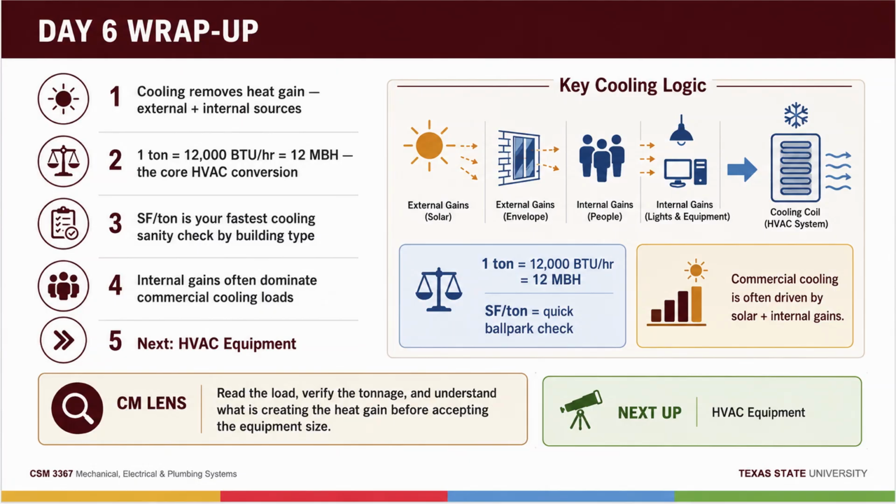Plain language. Common ways to lose points. Learn them now. Using R values straight in the equation without flipping to U. 1 over R, always. Forgetting 3.412 and treating watts like BTUs. Leaving out the latent loads entirely and dividing by the wrong constant at the end. It's 12,000, not 1,000. Show your work on everything. A right answer with no path gets partial credit at best. Because in this business, a number nobody can check is a number nobody can trust.